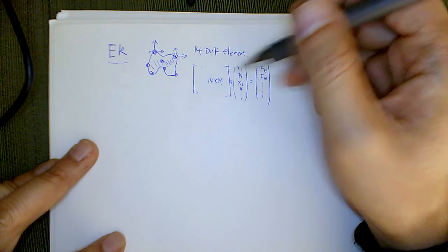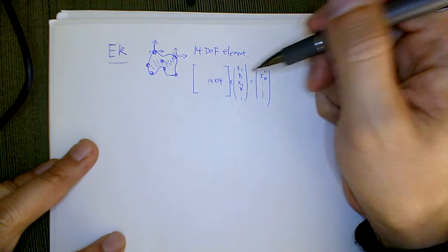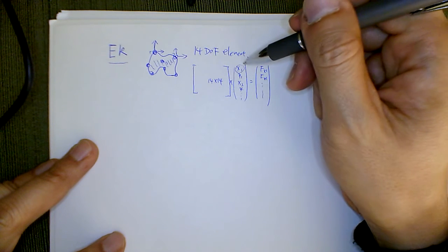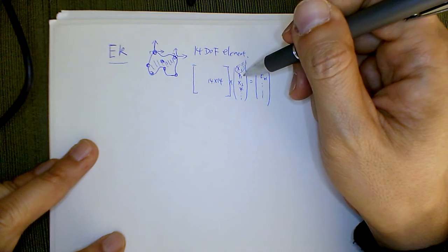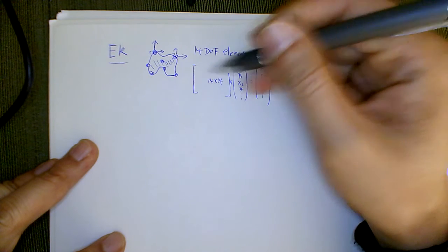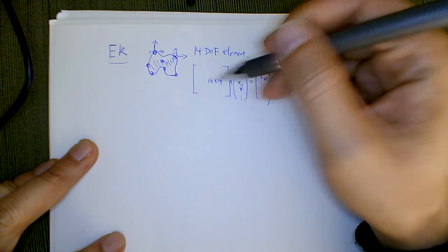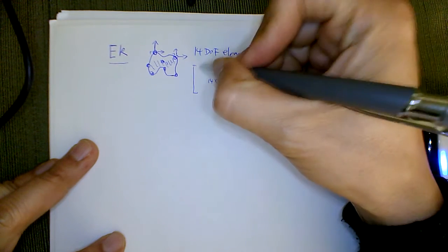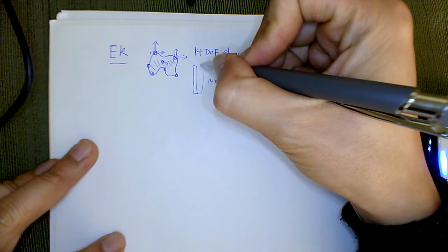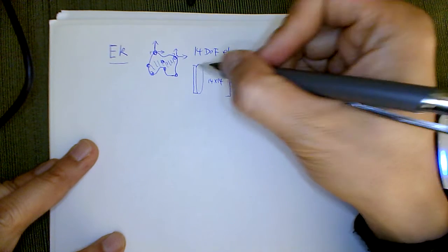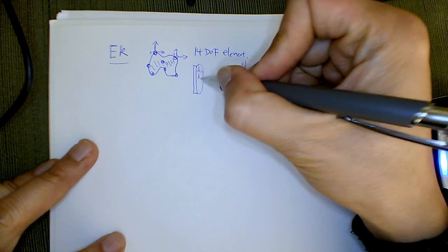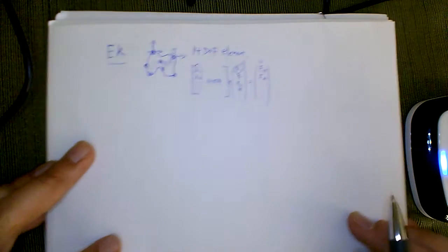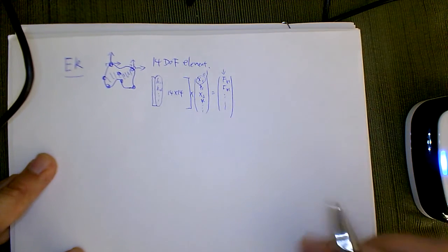Then we talked about the definition. If you keep x1 equal to 1, but everything else is 0, then you do the multiplication and go through the matrix. What do you find out? The force you get will be exactly the same as the first column of your stiffness matrix: K11, K21, and so on. That provided us a way to physically find the element stiffness matrix.